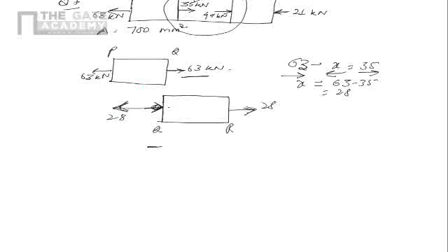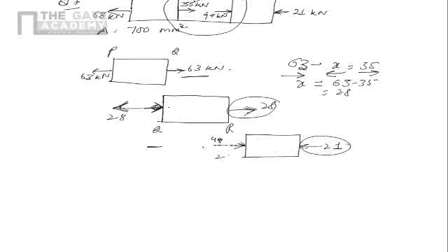Now let's see whether this balances out from the other side also. So I take the third segment. This is a 21 force here which is given, and we know that the net force is 49 this way. This is 49 here. It is provided to us. So how will it become 49? There is a force of 28 already acting plus 21 more, which is nothing but the balancing force of 21 here. So obviously this 28 is the right answer.